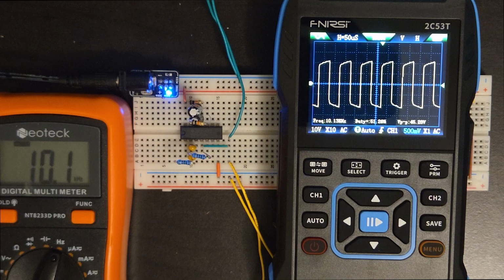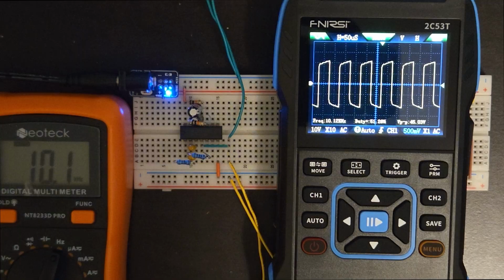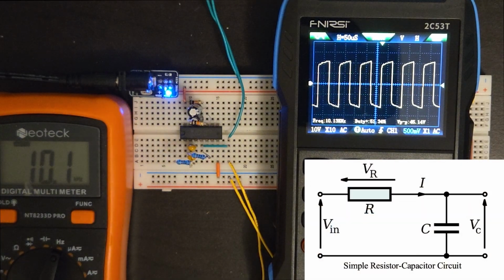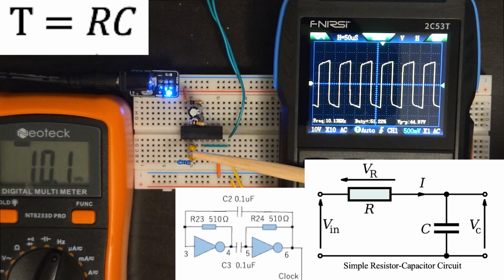But there are other ways to calculate these values. If we use the simple RC time constant for a simple resistor capacitor circuit, where the period is equal to R times C, we can use that for this circuit with two simple resistor capacitor circuits.